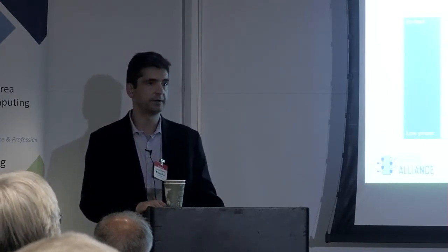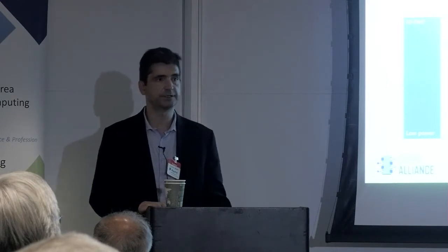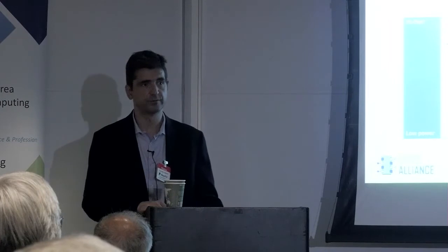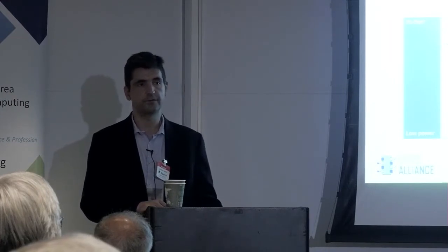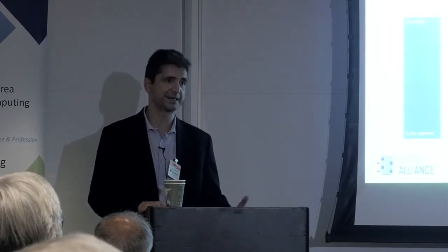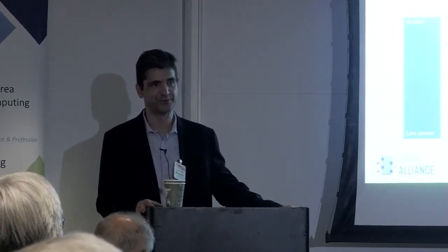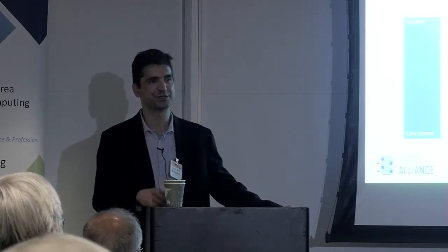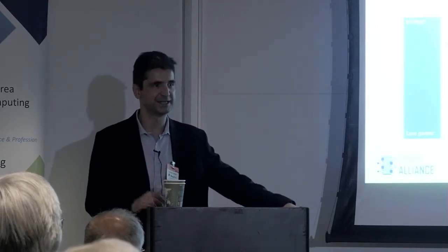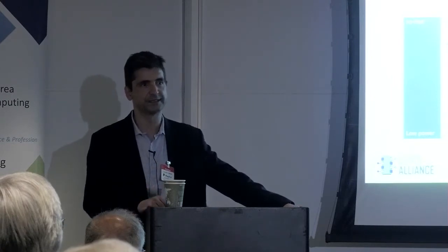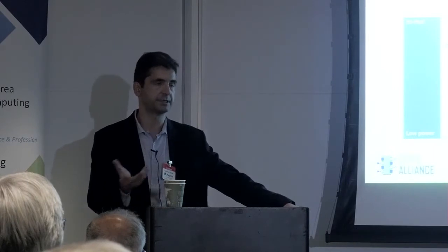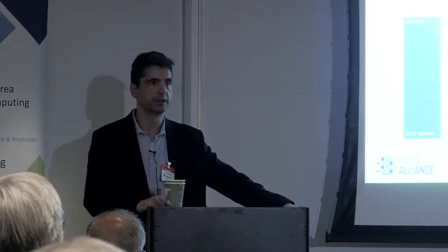Typically what we've done is run in parallel the RTL simulation with 3 commercial tools and 1 open source tool, Verilator. And we do aggressive testing through the whole space of possible scenarios, including random generation of instructions, interrupts, CSR states, stop and go, etc. And we do the comparisons between the RTL simulation and the golden model.